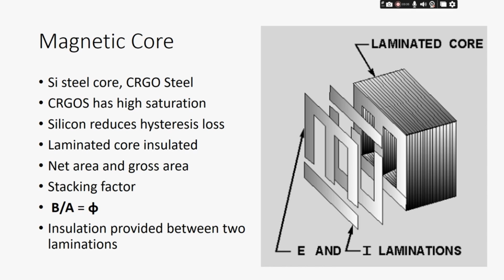Next, this core. So the core is made with laminated sheet. As in the definition of metal, some metals can be used to make a thin sheet out of it. So here this comes in useful. Each particular sheet will be insulated, that means they are not connected, insulated through some insulating coatings, and here different types of laminations can be used.